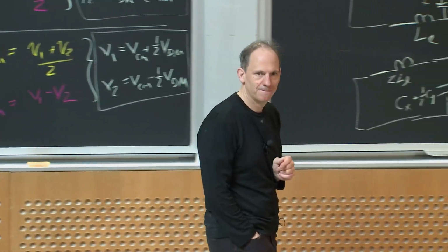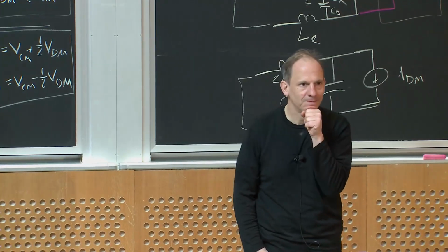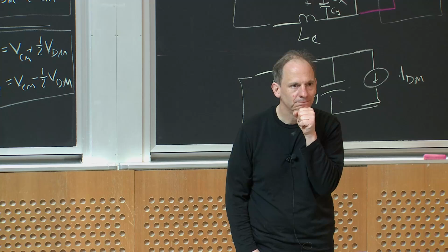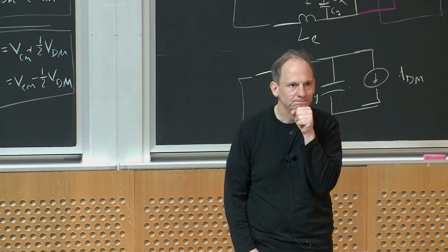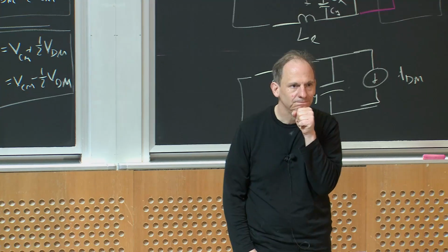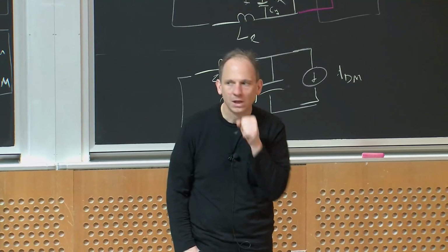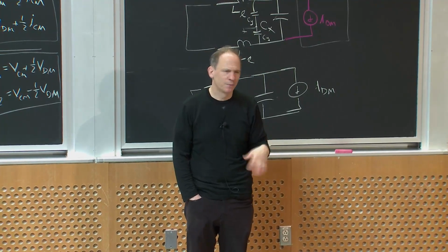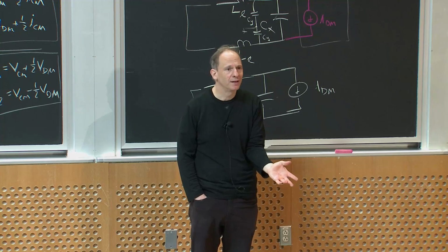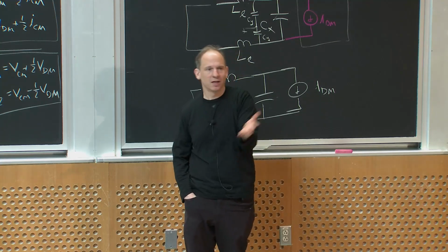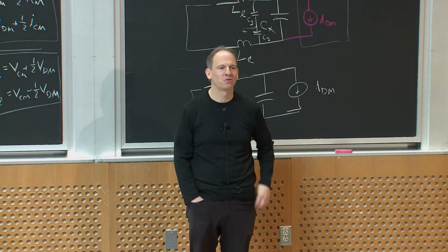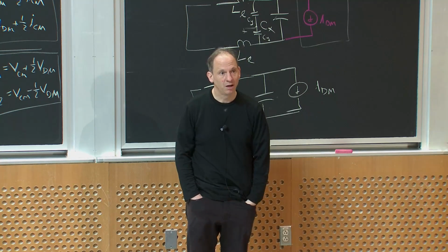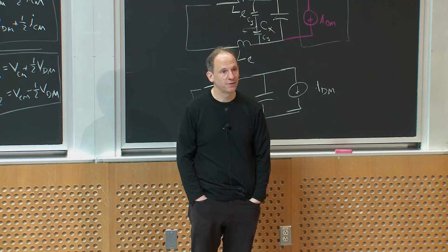Any questions? Yeah. So the common mode and the differential mode, do they both occur simultaneously, or are they situations that occur separately? Well, different things might drive common mode and differential mode noise, but typically they're occurring together, right? And it's just a question of what you're seeing on pin 1 and what you're seeing on pin 2 in terms of voltage and current. So they occur together, but what's dominant may depend upon the situation, right?